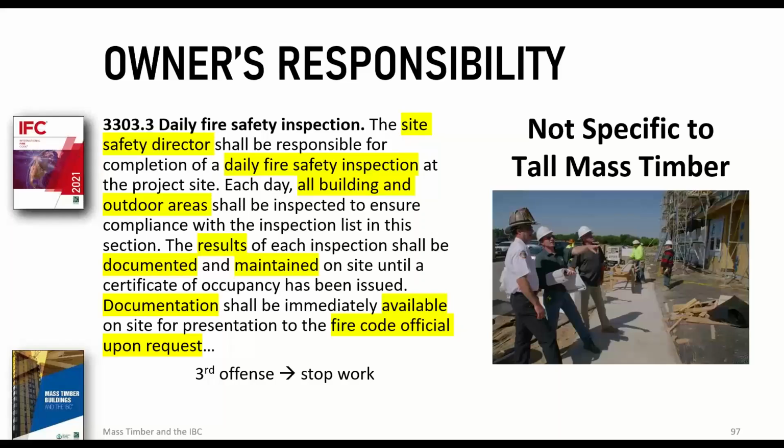The results of each inspection shall be documented and maintained on site until a certificate of occupancy is issued, and it should be made immediately available to the fire code official upon request. If they ask, and on the third time they've asked, the people on site cannot produce it, the fire department will have the legal authority to issue a stop work order, which in a lot of jurisdictions is groundbreaking, because you just don't see fire marshals' offices issuing stop work orders traditionally around the country. It's usually a building department function. And the fact that they have to do this every day until their C of O is issued is important.